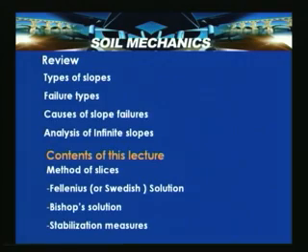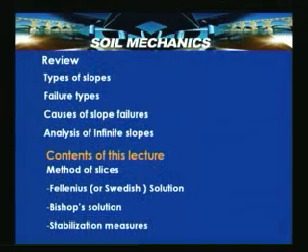But we discussed that the demerit of this method is in finding the weight of the entire portion of soil which is subjected to failure, and its CG location. So, in this lecture we look into the method of slices, specifically the Fellenius or Swedish solution, and thereafter Bishop's solution. Then we discuss some stabilization measures involved in improving the stability of a slope.